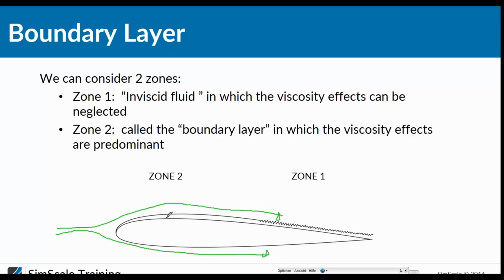The reason is that we have friction, viscous effects inside the flow, and here at the surface of the wing, the velocity is 0. So here we have a stick condition, which means that here the velocity is exactly 0. And if we go far away from the wall, somewhere we will have the outer flow velocity.